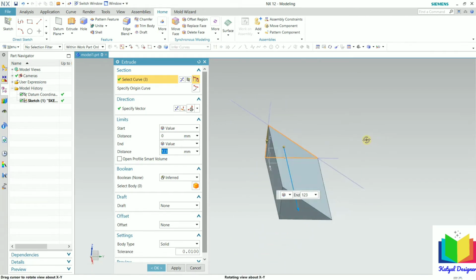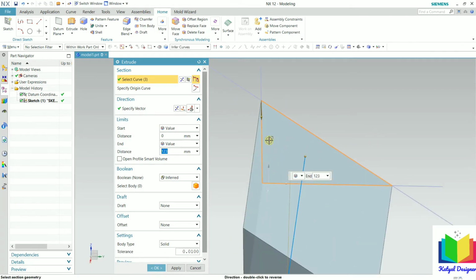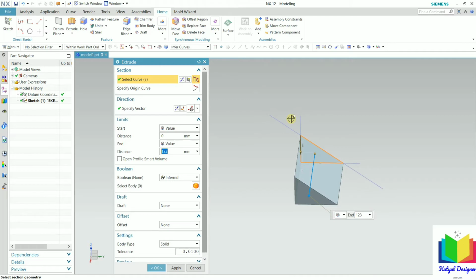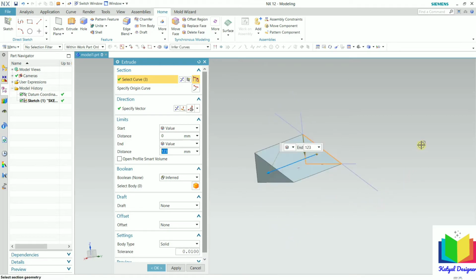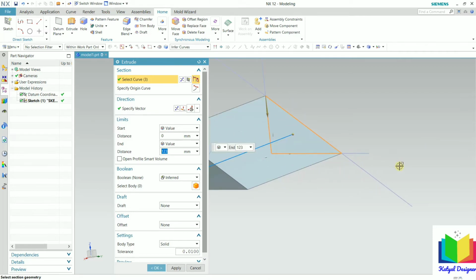creating the extrude of this solid section. So in this we can see we have this closed section. It has only created the extrude of this. For the other remaining parts, the extrude has not been created. So it is the reason because we have a closed sketch and here we have an open sketch. So that is why we should always avoid the intersection of geometries.